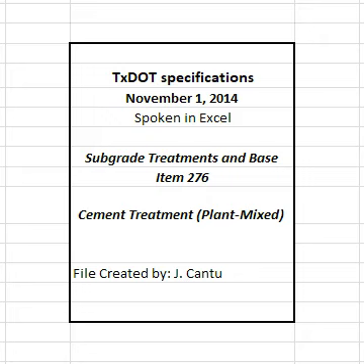This price is full compensation for furnishing and disposing of materials, including cement and base, storing, mixing, hauling, placing, sprinkling, compacting, micro-cracking, finishing, curing, and maintaining and reworking treated base, and equipment, labor, tools, and incidentals. Sprinkling and rolling, except proof rolling, will not be paid for directly but will be subsidiary to this item, unless otherwise shown on the plans.